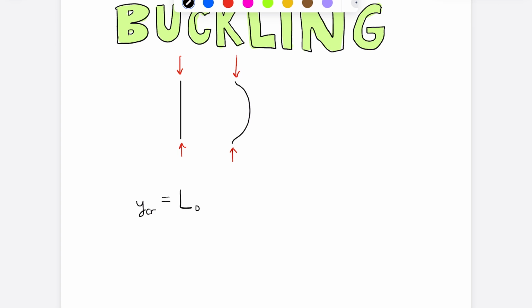And it's equal to the free length times this C1 prime constant times 1 minus, parentheses, 1 minus C2 prime divided by lambda effective squared, to the 1/2 power.